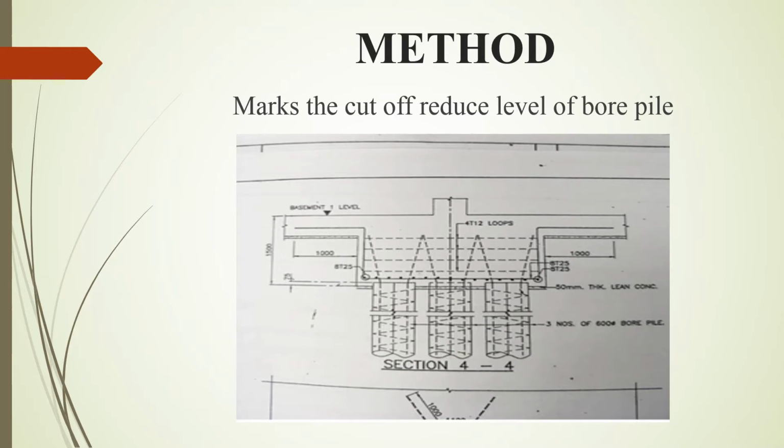Mark the cut-off reduced level of the bore pile. Before the contractor proceeds with the footing work, the finished cut-off level of the bore pile should be marked on the bore pile. The finished cut-off of the bore pile is indicated in the construction plan. The surveyor will calculate and mark the cut-off level based on the construction plan. A temporary benchmark will normally be established at the construction site by the surveyor.